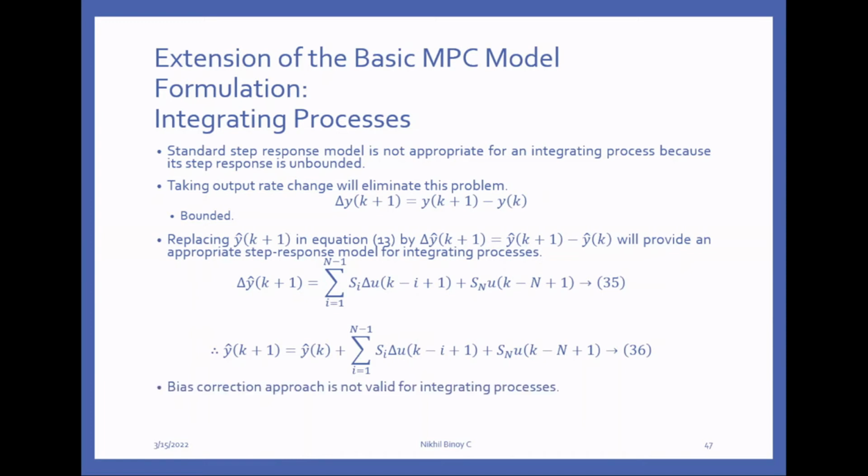Now similarly we can do bias correction. I'm very sorry, in this way we can't do bias correction. That is not possible. The bias correction approach is not valid for an integrating process. Several modifications are available, but those are not as simple as the prediction. Okay.